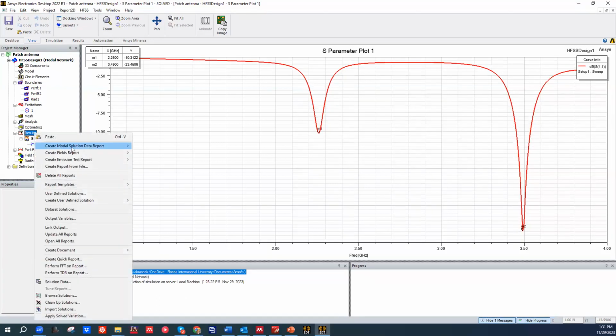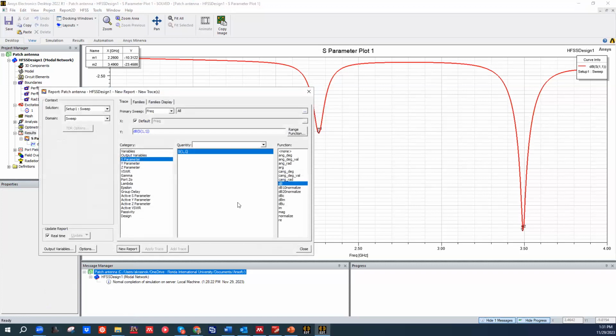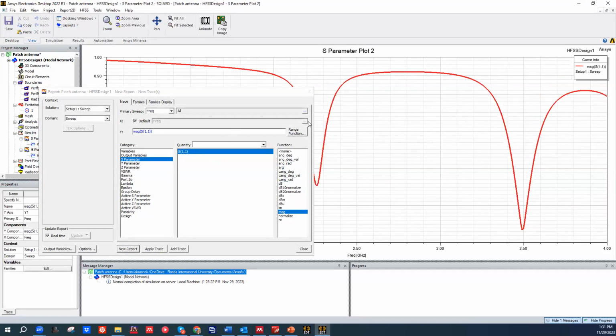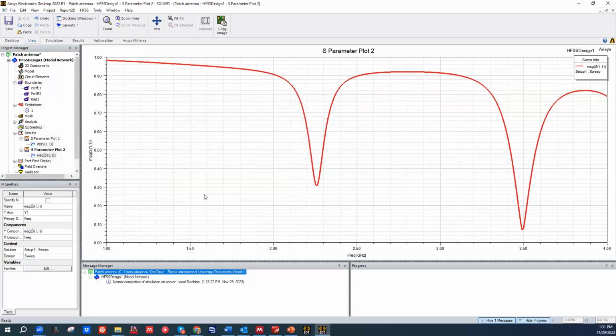So if I create the same but in the magnitude, in the linear scale, I will see that my antenna, in terms of amplitudes of the field, radiates 70% of the field, right? And if you square this number, it will be some number in power. So it's still 70% of the field, and it works okay, but not perfect.